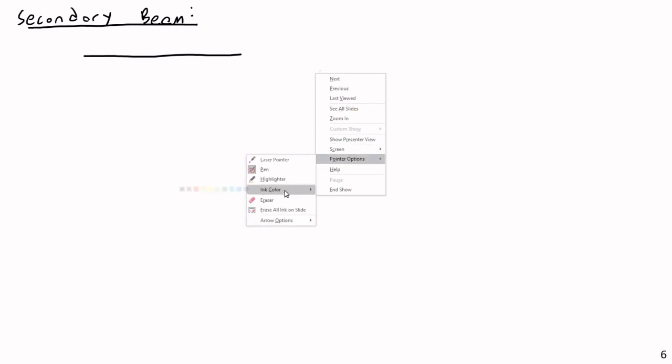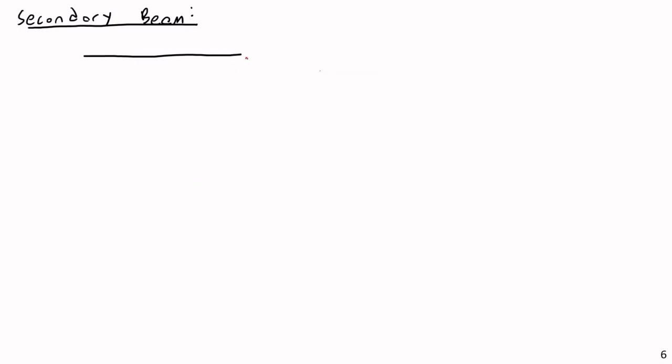I'm going to impose a unit load on joint C, or on point C. The reason I'm going to draw this downward is because I know the deformation is going to be downward. That's not a point load P, that's a 1 kip load. I know it's going to be deforming downward, so I'm just going to predict that this force is downward. If you think of mechanically how a pier settlement works, the pier is pulled downward, and that pulls the rest of the beam with it.